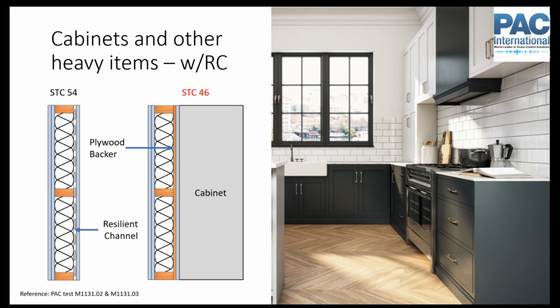So you'll put half-inch OSB or plywood there, either between, or I've seen it sometimes in place of the resilient channel, where the cabinets are going to be mounted. The contractors will put that there because when the cabinets are installed, they're typically screwed through the drywall and into the studs. And if you didn't have this spacer there, then as they're pulling them in tight to the studs, you'd start to crush that gap where the resilient channel is. So they put this in basically just like a spacer.